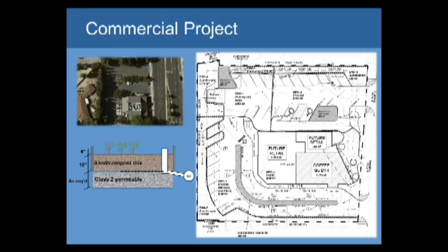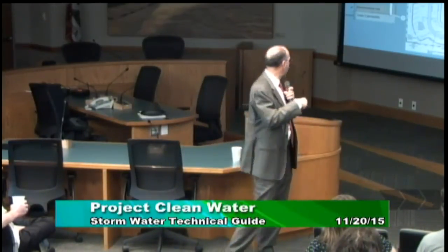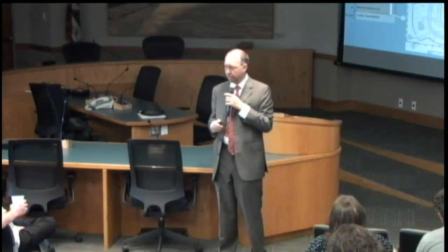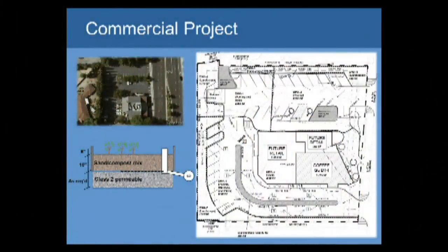So what I did was to take this, which was developed for that 4% sizing factor, and see what happened if we plugged this in using the PCRs. And the answer is that these two worked out just fine, reasonable depths. This one, which drains this whole area here, ends up being pretty deep. You end up with about 5 feet of depth. If you just use gravel, you could obviously make that smaller, either by using our facility with the orifice, or by possibly putting in buried pipe or something in order to create more efficient underground storage inside that gravel layer.